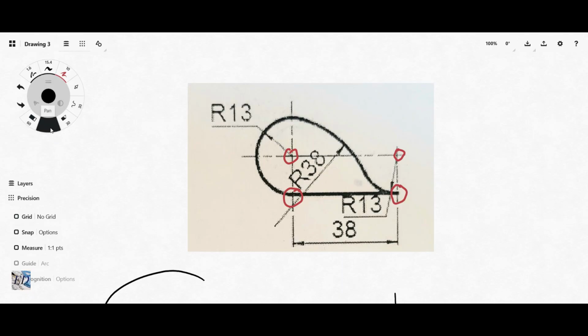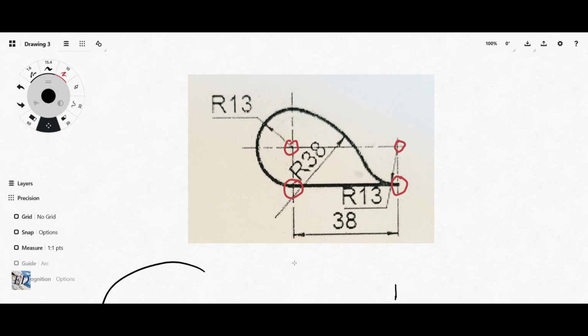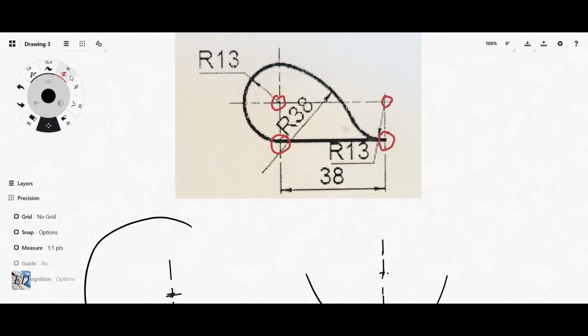Yes. So let's start with the end that touches externally, right? This edge here. We are trying to find the center point for this particular arc, and using the tangency rules, the distance between the center of this arc and this particular one is the sum of the radii, because they touch externally. That is one of the tangency rules.